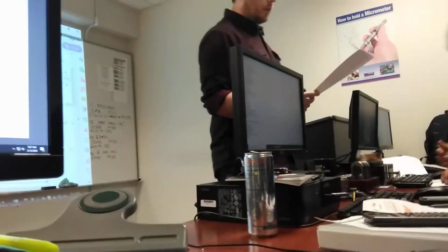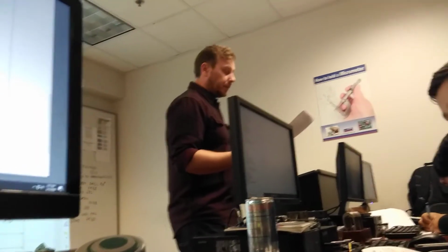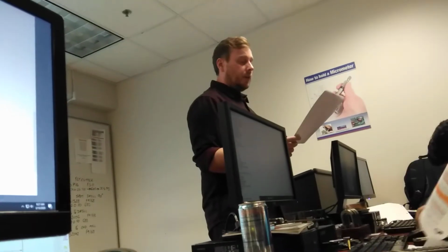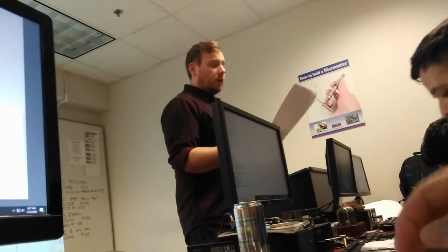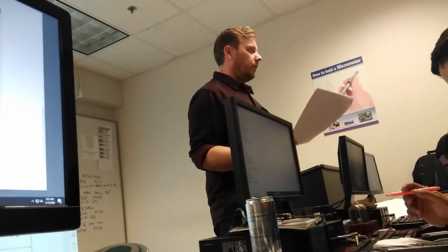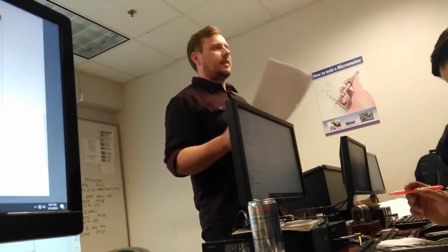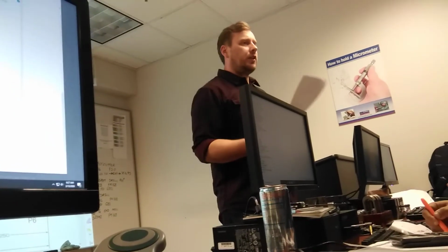So, if the programmed cutter path needs to climb cut, which is what's usually desired on CNC machines, since the machines are rigid enough to handle this type of cut, and the conditions from this type of cut are usually preferred, highlight this part. It will then be programmed with G41. So in order for you to climb cut on a CNC machine with a right-hand tool, you've got to use G41.